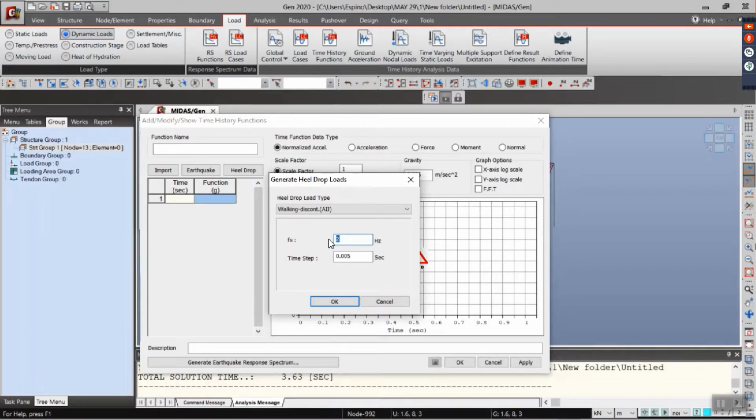This is because the vibration amplitude by resonance is increased when the two frequencies match or are at a multiple. Since the frequency of the floor is 3.9286, we can consider it approximately 4 Hertz. So in order for resonance to occur, the frequency must be approximately 2 or 4 Hertz.